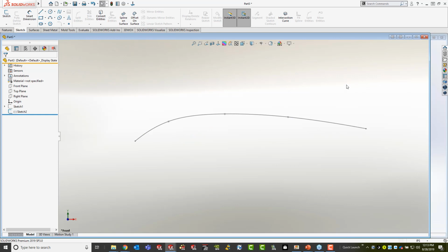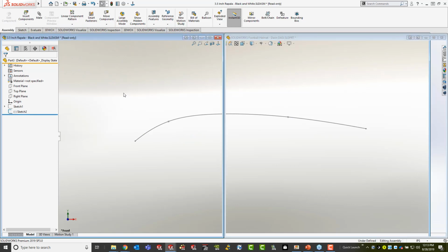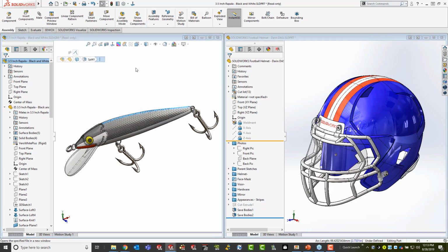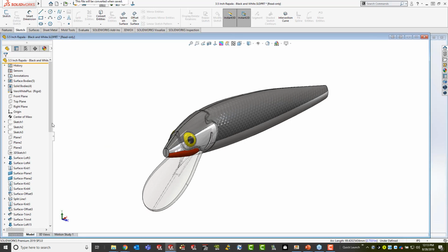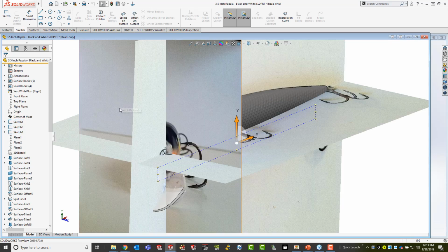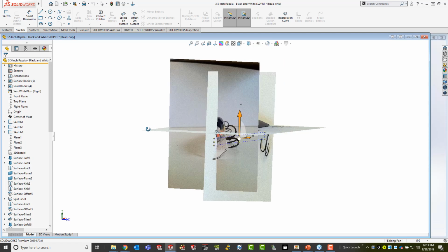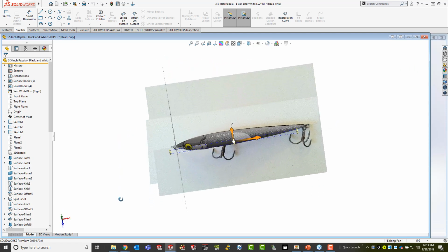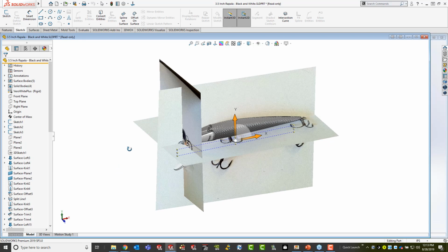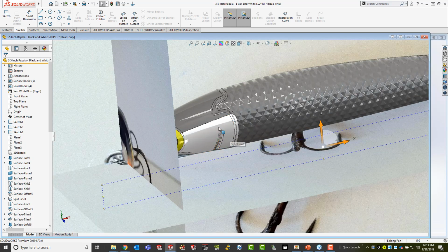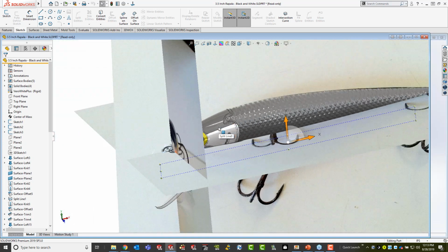Now rinse and repeat on that process from multiple directions, and what you basically end up with is the use of that picture creating the 3 different plan views coming together. So in this particular location, what I had is 3 sketches, and each of those 3 sketches actually combine to give me those angles of attack. So just by grabbing sketch planes, maybe creating a surface and then lofting or projecting those different sketches onto those surfaces, that'll enable you to create other references like these gills directly from that 2D image.